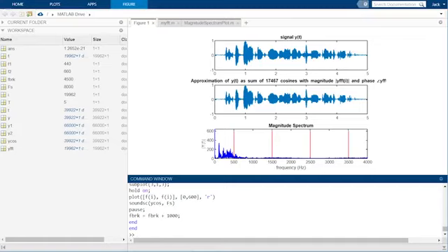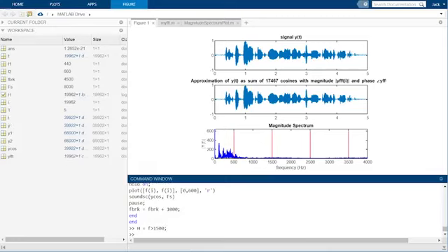For example, we can define a high-pass filter that will let all frequencies greater than 1500 Hz remain in the signal, while removing all other frequencies. It is called a high-pass filter because it is designed to let all the high frequencies pass through it while filtering out frequencies lower than 1500 Hz. This filter H is equal to 1 for all frequencies greater than 1500 Hz and equal to 0 otherwise.